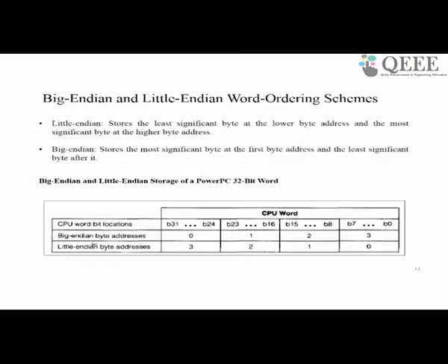But normally the memory interfaced with the processor is byte addressable, which means every location in the memory stores only one byte. So the 32 bits being read by the processor have to be stored in four different memory locations, which are usually successive. Suppose we store 32 bits, comprising 4 bytes; then we should make use of 4 successive locations.